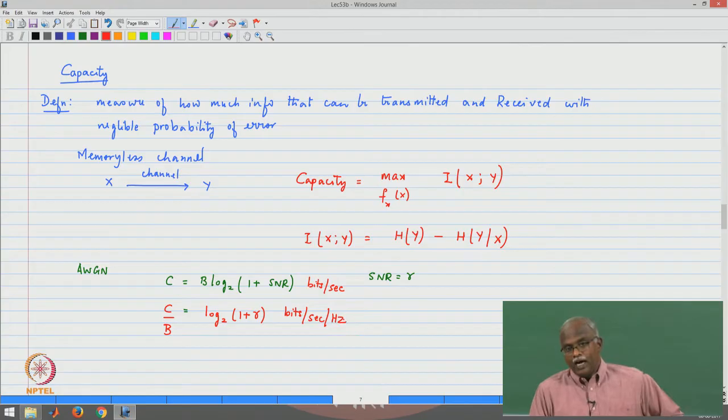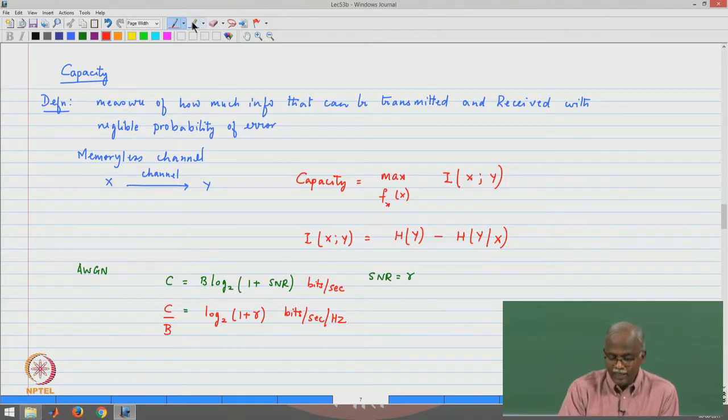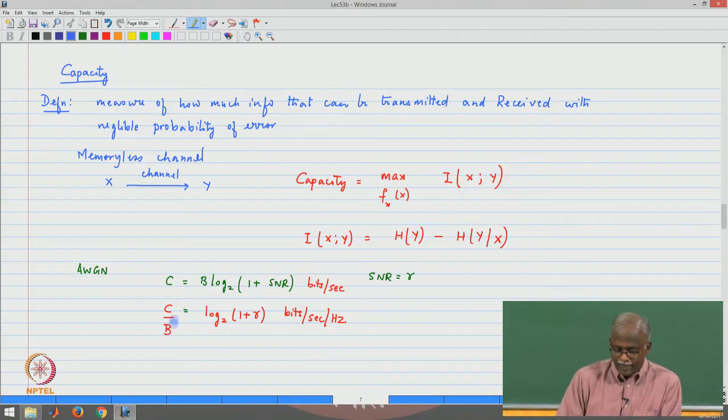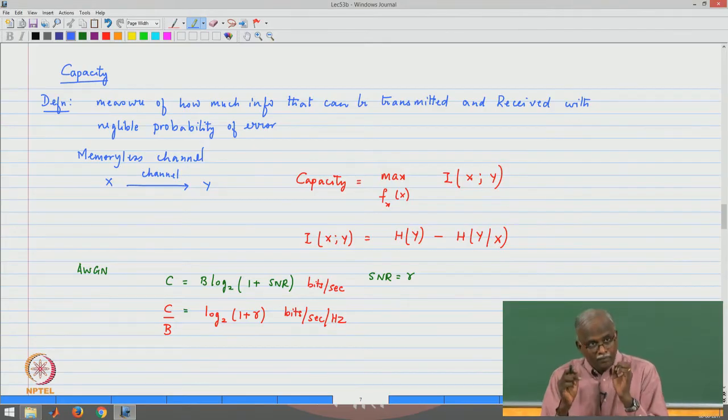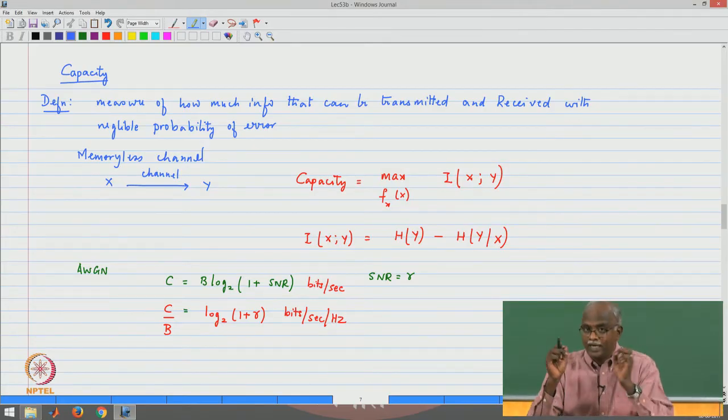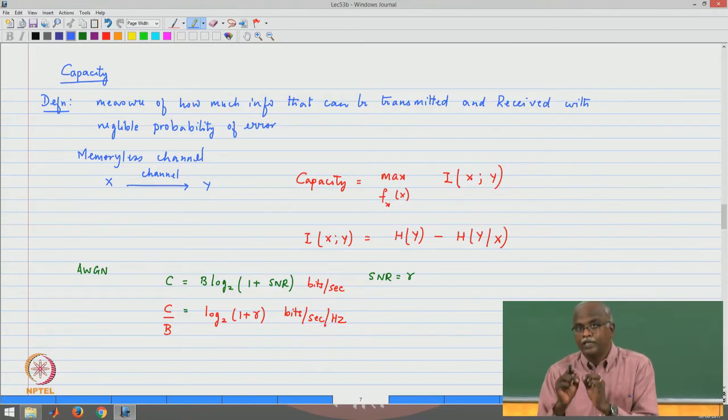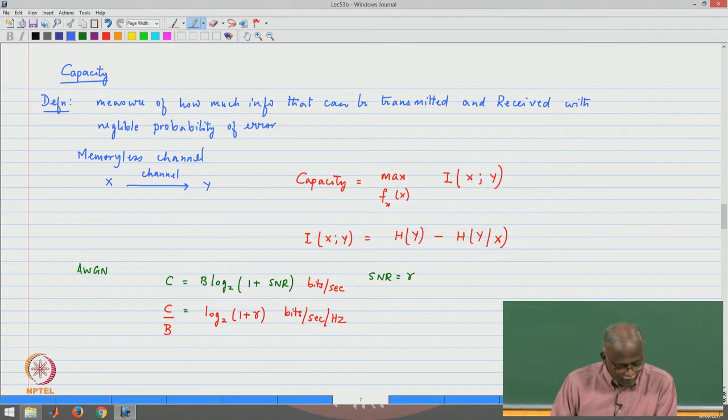Okay. So, that is our basic definition of capacity, and this is derived from first principles using the definition of capacity in terms of mutual information, in terms of entropy, and this is what we often refer to as Shannon capacity. This is the expression that we have used quite extensively when we were talking about the capacity of a wireless channel, when we had one transmit antenna, one receive antenna. Now, we are going to extend our understanding to the case where we have multiple transmitters, multiple antennas.